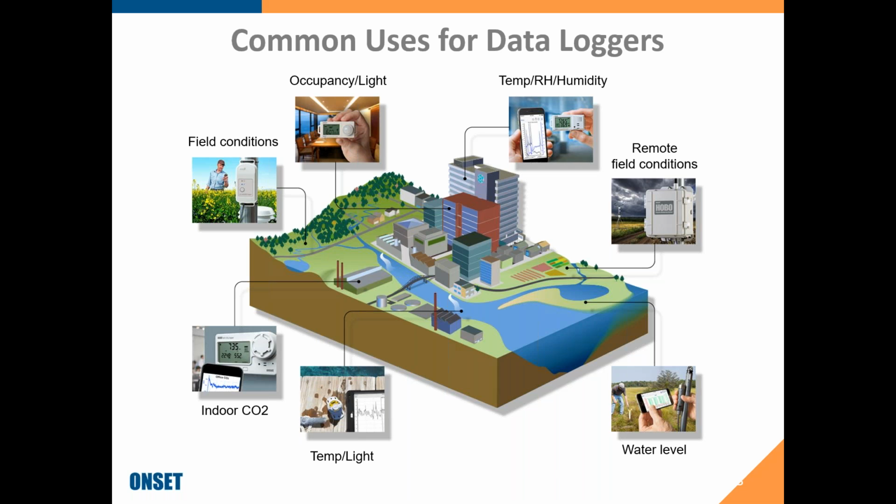At 5 o'clock, we have water level data loggers. We have several different styles of those, based on if you're visiting the site and pulling them up, or you need a whole lot of them. Groundwater wells are typically using Bluetooth now. The top end is in air, the bottom end is in your well, and it saves you from having to remove a data logger or pull it out of a well. It's just going to find it on your smart device so you can read that out. And these can stay deployed for over a year with user replaceable batteries, and they last about a year. And you can replace the batteries.